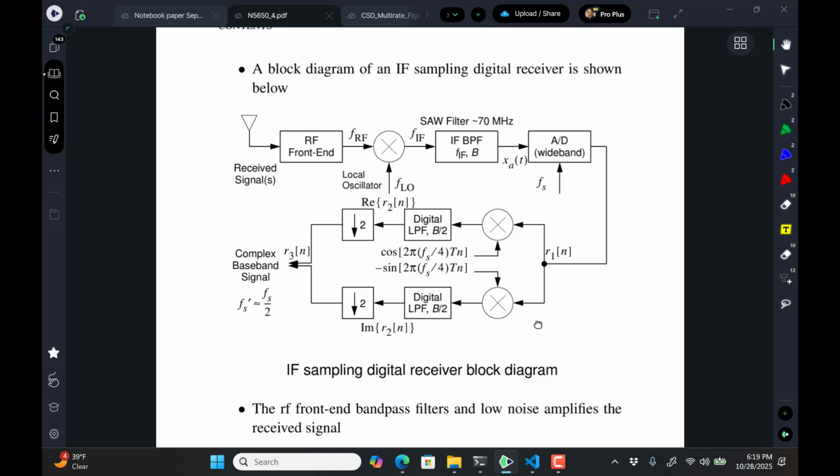I think it's a microwave filter, but surface acoustic wave means you take a substrate, generally lithium niobate. Why do I know this? Because I had a class and we talked about that material. And you pattern it with some metallization and you launch a wave on it, but rather than it being like microstrip for a transmission line, it's actually an acoustic wave that travels across the surface of the substrate.